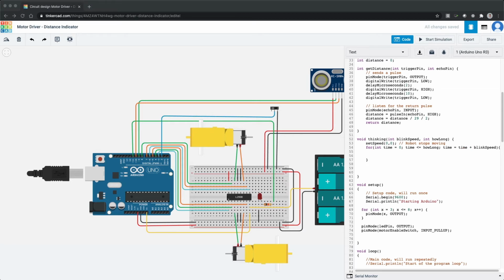To determine how bright the LED is, we will make use of random values. Since the LED is an analog output, the value can range between 0 and 255. Type int randValue = random(256); Here we just created a random number for the LED value and called the random function to generate a number.